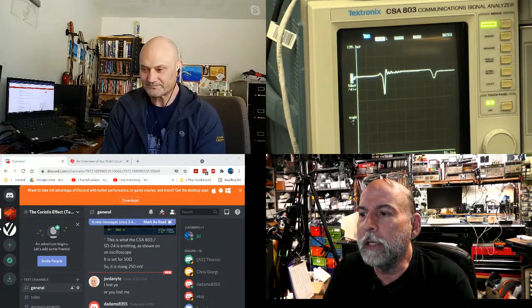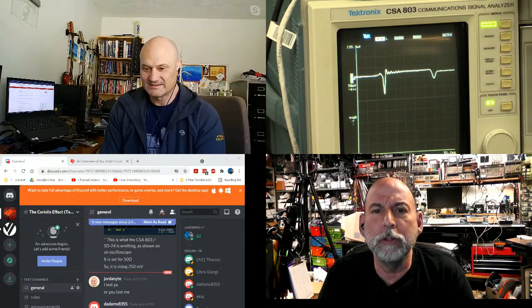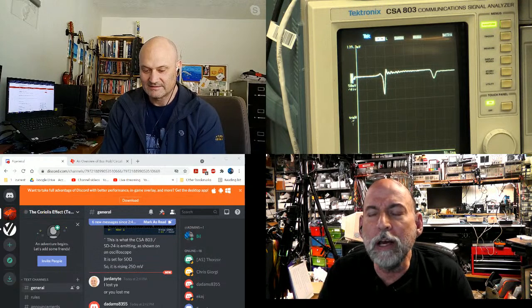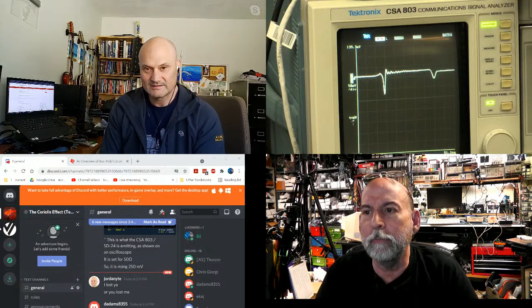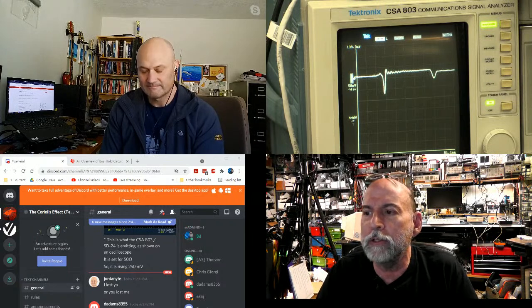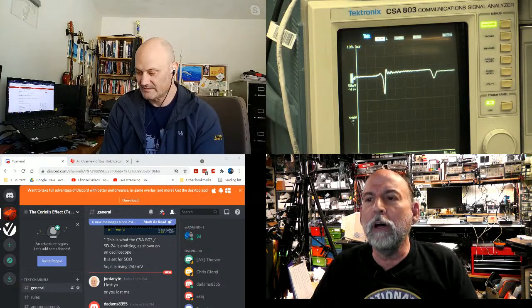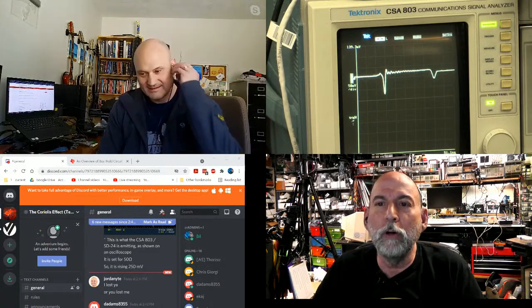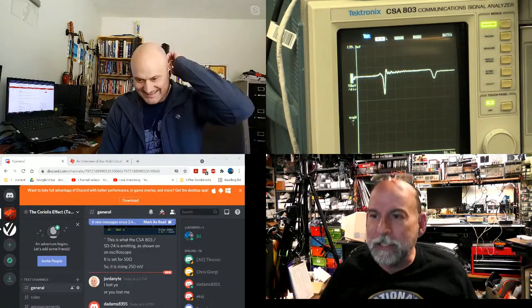So what always goes through my mind when I talk about heat is, how much current would you be pushing through a PC board? In the old days, not a lot. We tended to do big heavy loads as discrete wires. But nowadays, if you have a 100-watt processor, and it's running off 1 volt, how many amps is that? That's 100 amps. That's a lot. Yeah, that is huge.